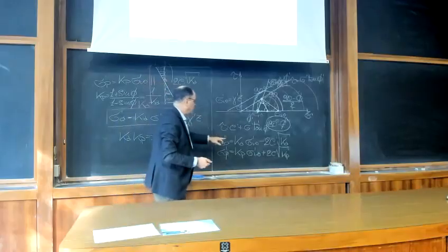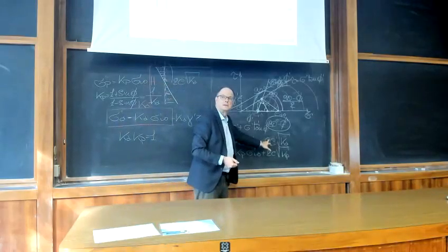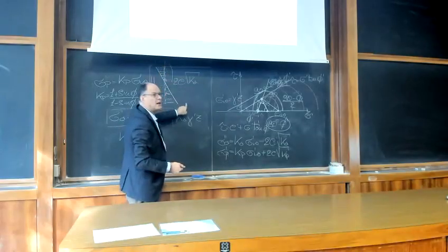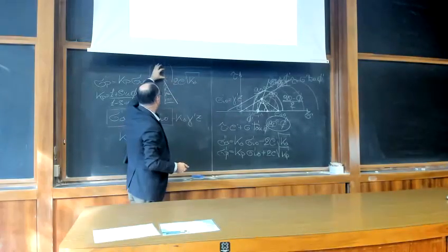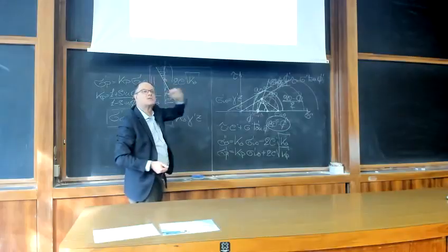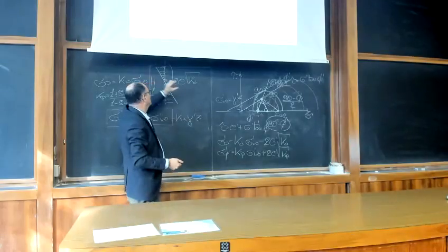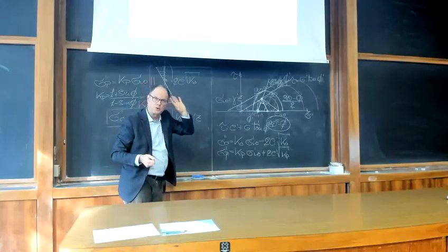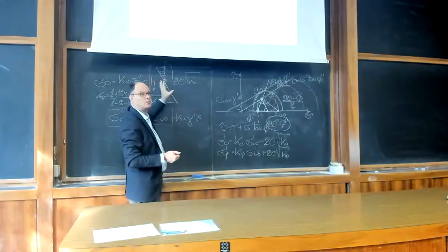But for a cohesionless soil, you don't have this, you just have a triangular distribution, so even a 1 meter or a 1 centimeter will have some wall, and you will have some horizontal pressure, and you need some wall.